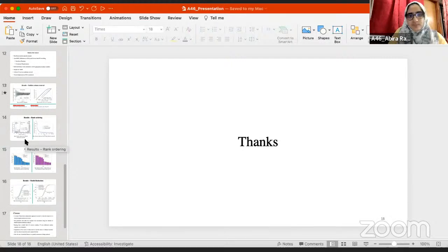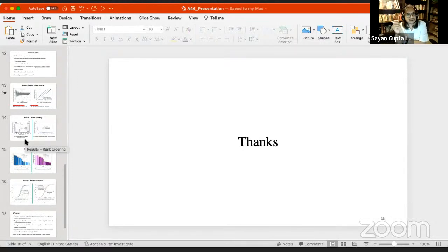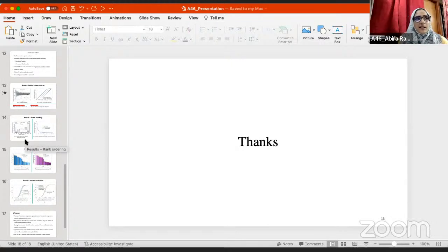No. Okay, so that brings me to the second question. Because of this sudden collapse, do you think that there should be some additional uncertainties that will enter into your model, which otherwise would not have been there? I don't think I can answer that question right now, because if I were doing an earthquake analysis on the structure, I would consider the same random variables that I'm considering right now. I have not considered any special random variables just because I'm doing a sudden column removal scenario. So maybe I can look into it, but right now I have not thought about whether any other different random variables will be more relevant as compared to a normal structure or not.